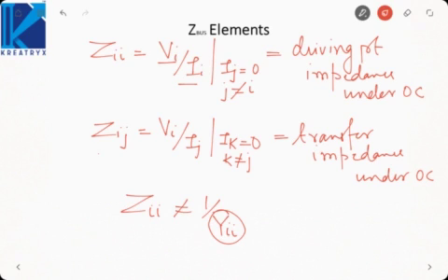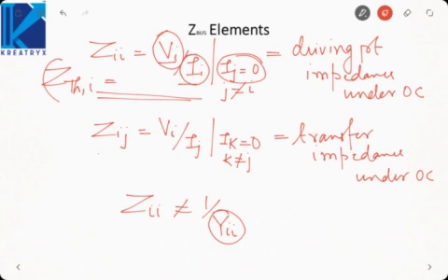What I am saying is, you open circuit all the current sources, then apply a voltage source at one bus and find the current through it, and the ratio of those two will give you the Thevenin impedance. Similarly, in this equation, I have opened all the current sources, then taken the ratio of voltage and current at a single node. So this is supposed to give me the Thevenin impedance at bus number i.